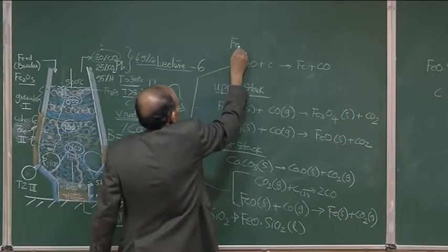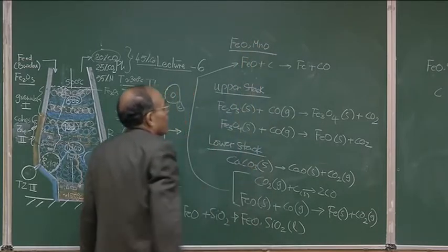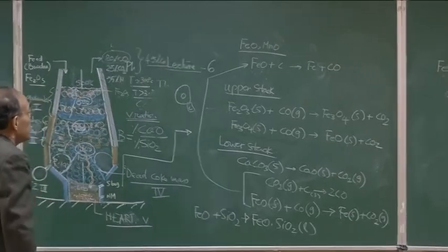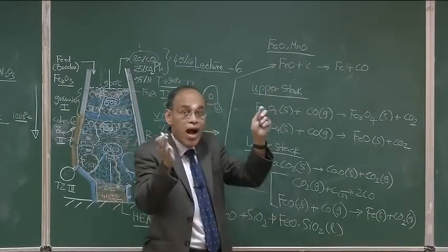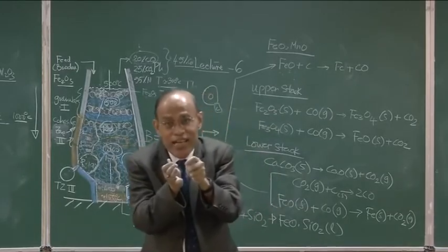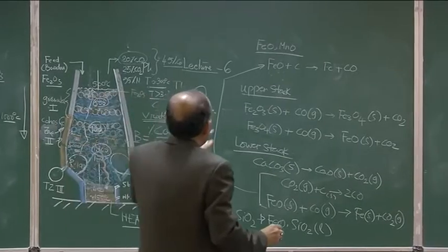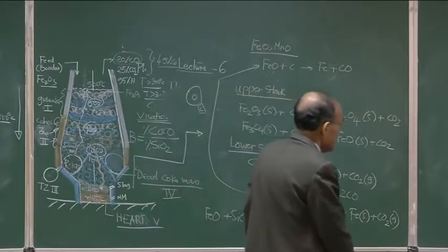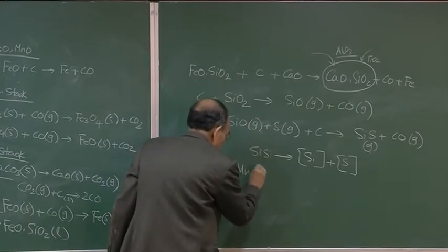So, the FeO and MnO, the manganese oxide which are present in the ore, these will undergo complete reduction, because again I said the phosphorus line, iron oxide line, Mn line, they are very close. So, high carbon potential and then high temperature will reduce.